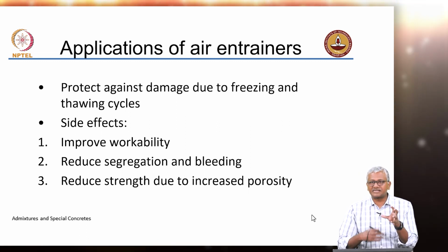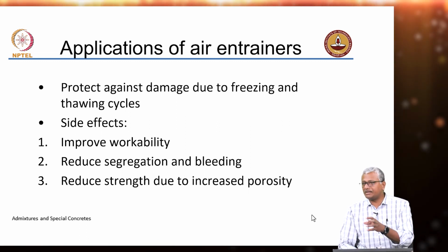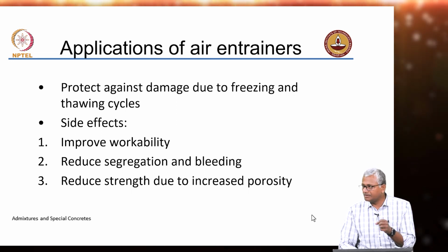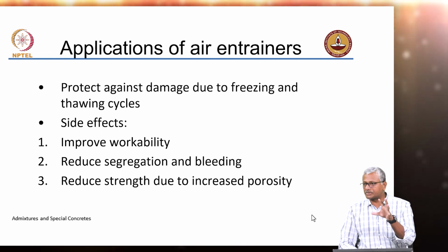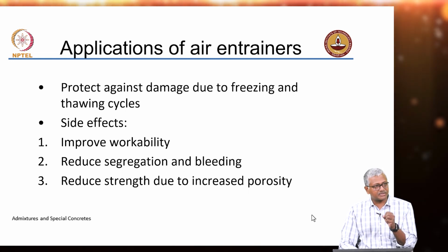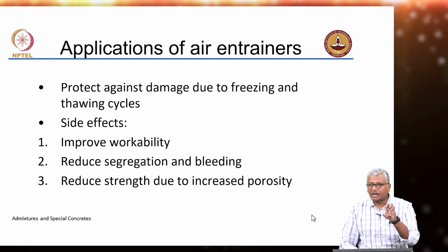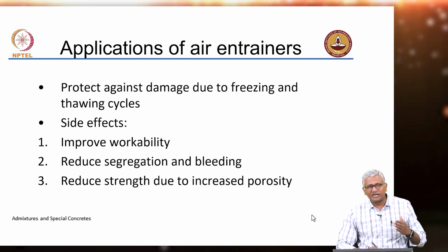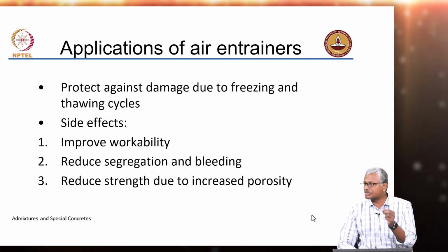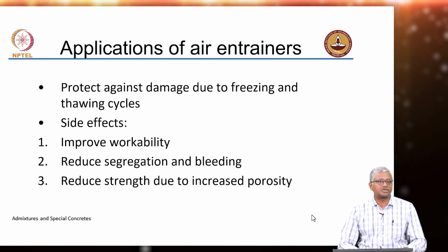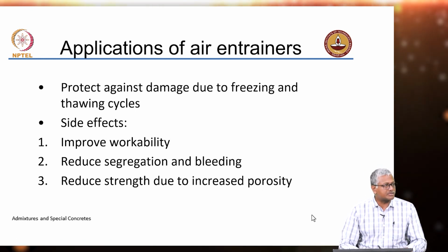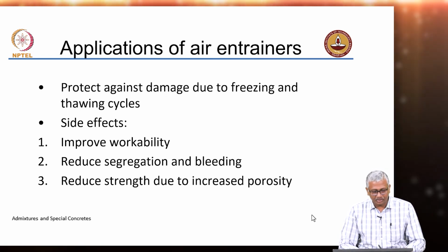Now, when this happens and subsequently the ice becomes water again, that is thawing, this water is essentially trying to move into the microstructure of the concrete. Whatever free water is there is trying to move through the pores up and down. So, this movement of water in the very fine pores is leading to the strain in the concrete. It leads to the creation of strain, and the resultant stresses lead to damage in the concrete.